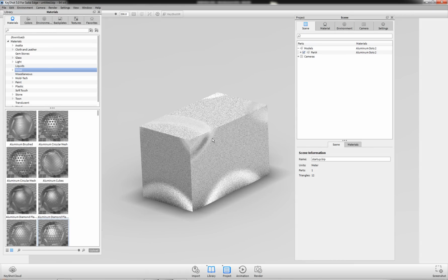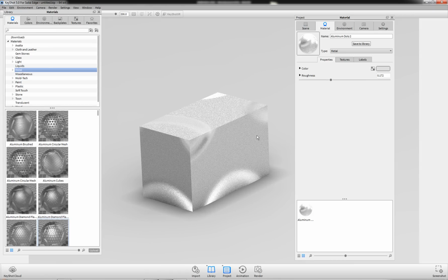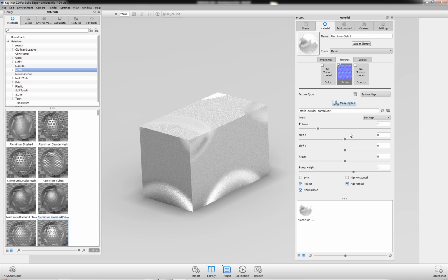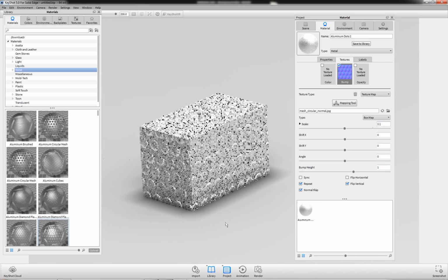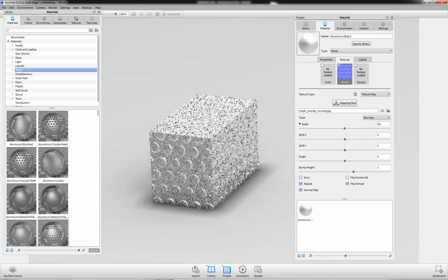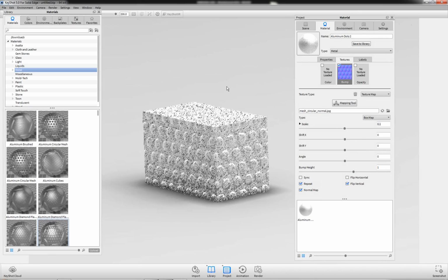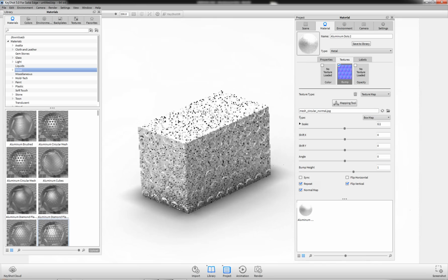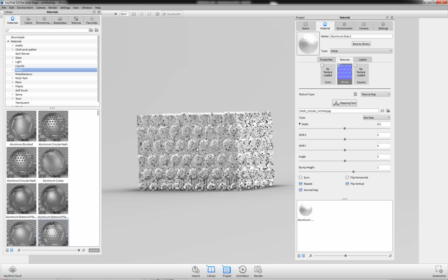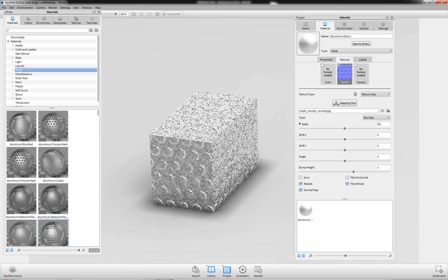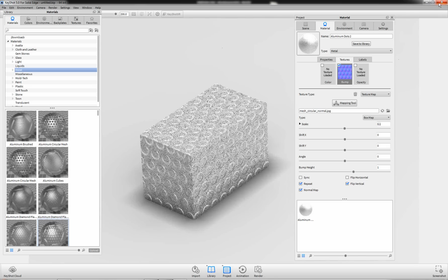The scale is a little big, so just to double click it, it actually takes you to the part model with the texture. So we're going to come over here and say, let's just make that 0.1. Alright, you notice as I pick one side, it automatically adds the dimples to every single side of the part. And that is just how KeyShot works. It just sees the face and wraps it around.